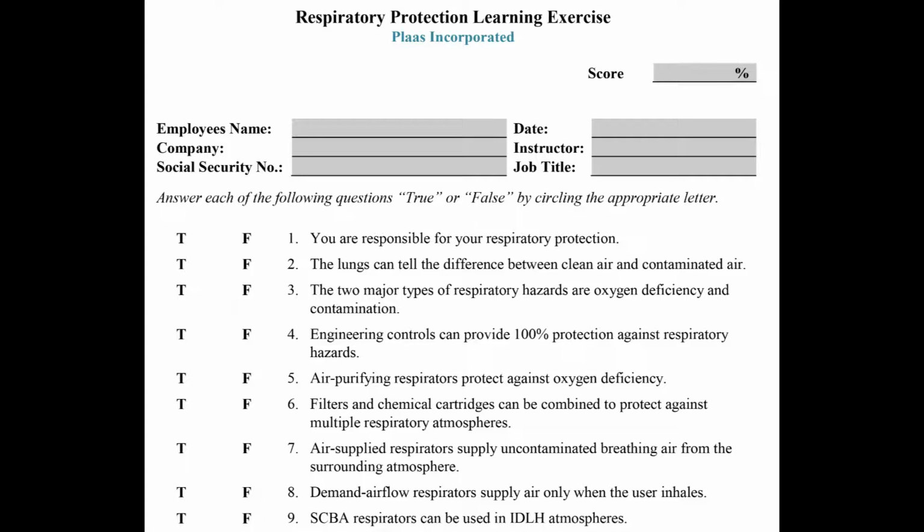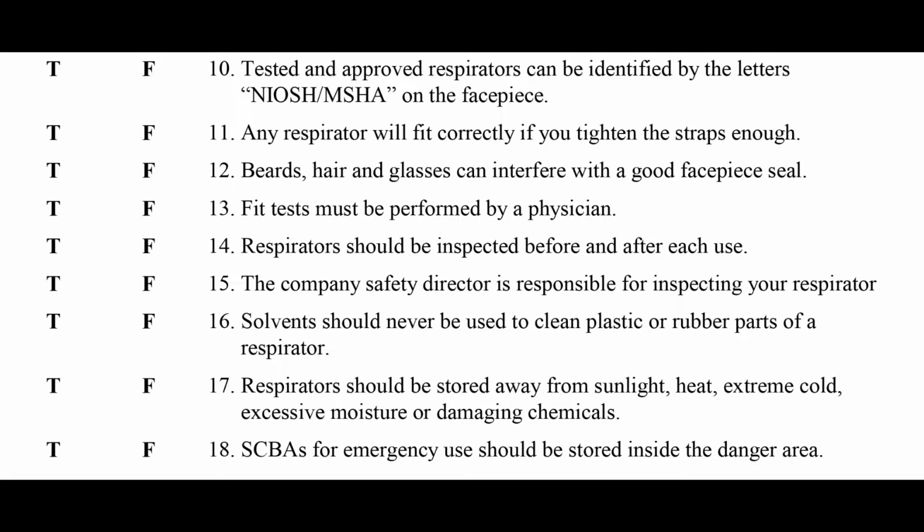Number 9, true or false? Scuba respirators can be used in IDLH atmospheres. That's true. Number 10, true or false? Tested and approved respirators can be identified by the letters NIOSH, MSHA on the facepiece. That's false. Tested and approved respirators can be identified by a number preceded by the prefix TC, for tested and certified. Number 11, true or false? Any respirator will fit correctly if you tighten the straps enough. False. Straps should not be over-tightened. If a good fit cannot be obtained, a different brand or size of respirator must be used.